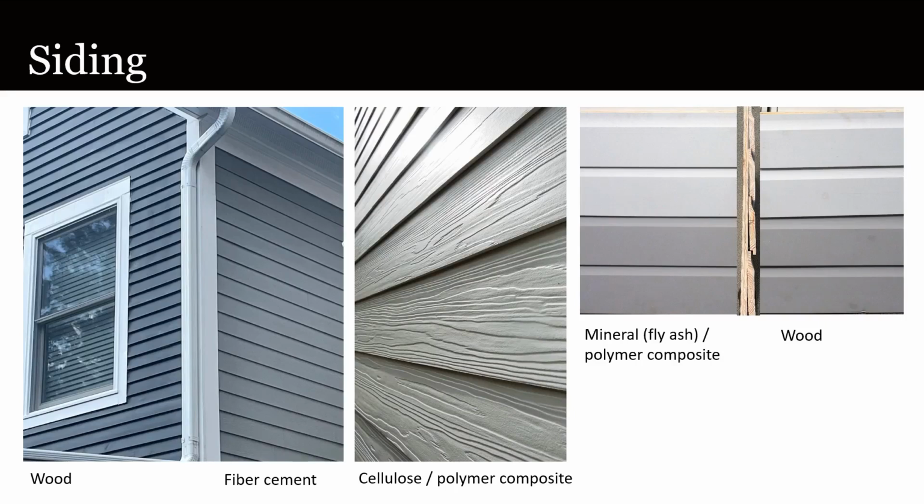even if the exposure was the same, the effect would not be a match because the shadow line at the butt edge is so obviously less. The shadow line is a function of the thickness of the material, which is limited by what is available from the manufacturer and cannot be adjusted or custom ordered in any other thickness. For fiber cement, the wood and wood fiber composite, that dimension is typically 7/16 of an inch, though there is the 5/8 inch material available in cement board.